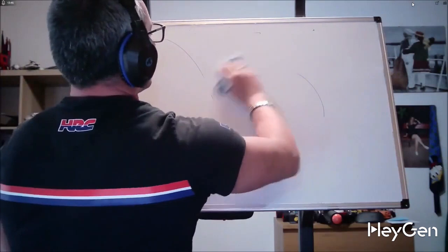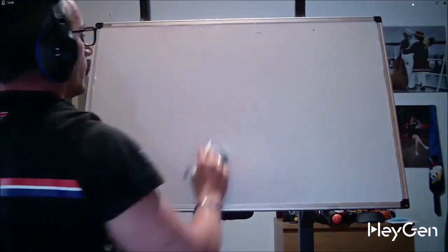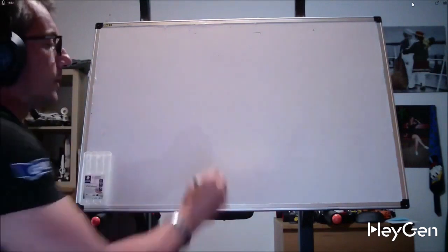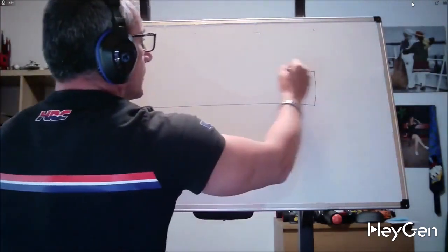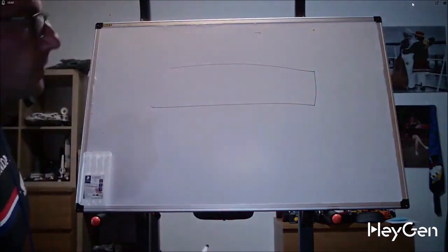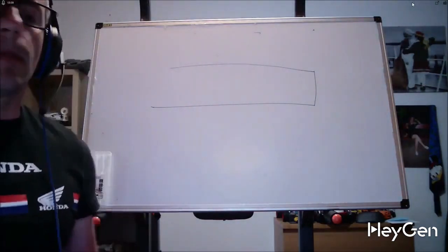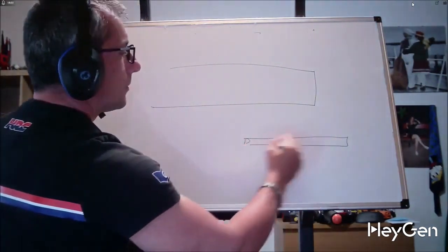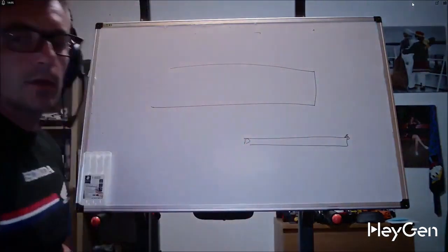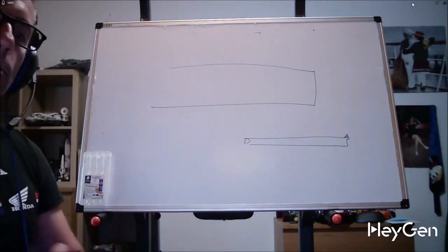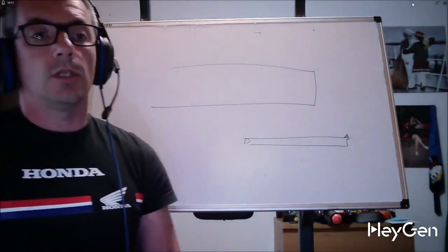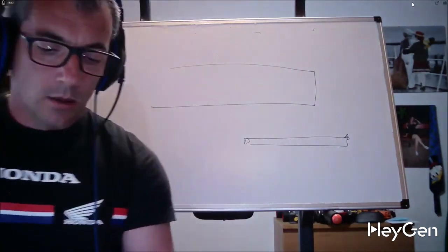Always remember that. I remember many years ago I had to make a hole, for example, and I couldn't find the solution in the insert, but I discovered the anti-vibration bar, a bar that extends 14 times its diameter. You put the insert here and it doesn't vibrate even if you push it. There is always a solution. You should talk to those who sell you the inserts. Never rely on incompetent people.